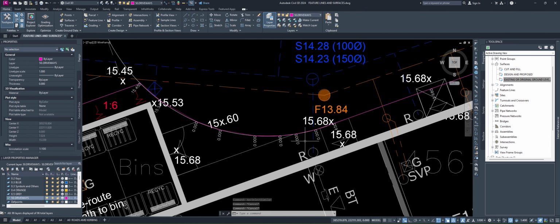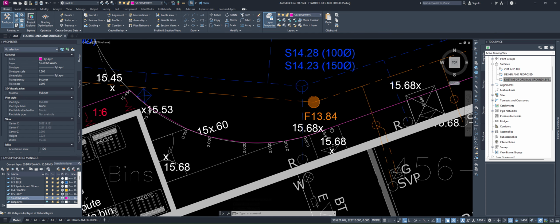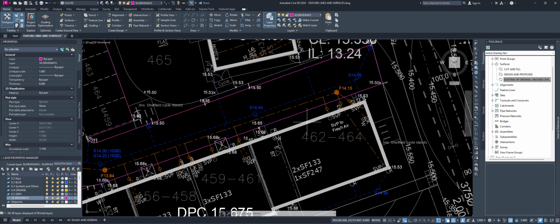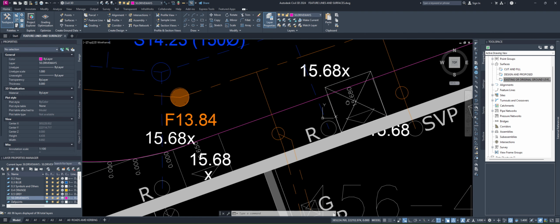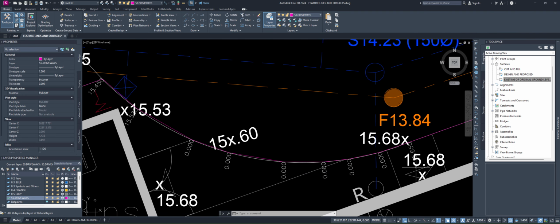Right, with this one so far, again, exactly the same process, similar to the previous one. We're gonna go between all the points with already applied elevation and regrade between the first point and second point where we have level, set grade along all the levels with non-given elevation between.